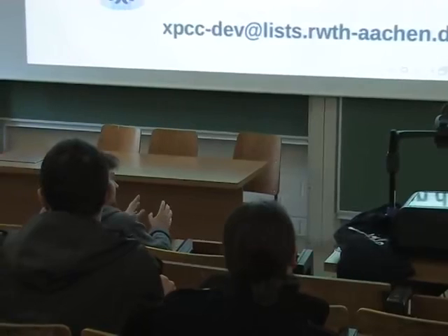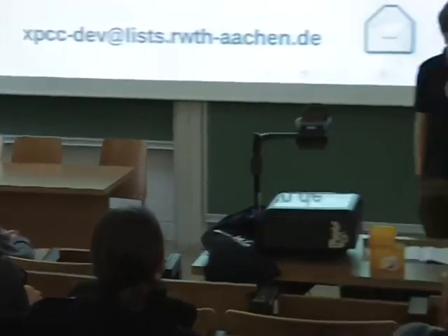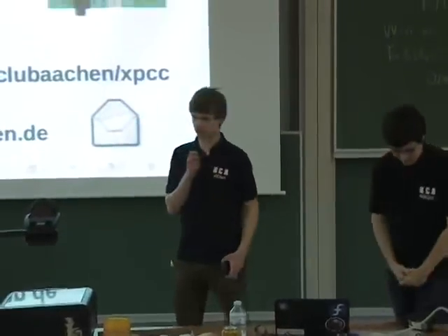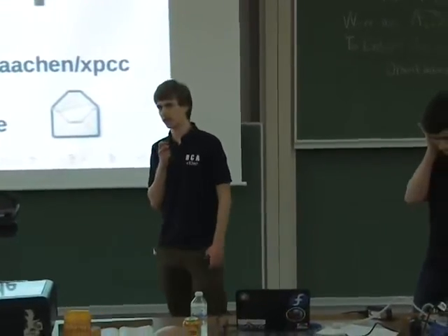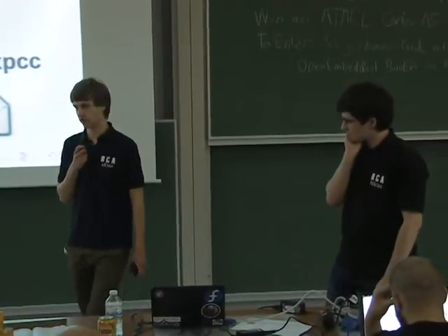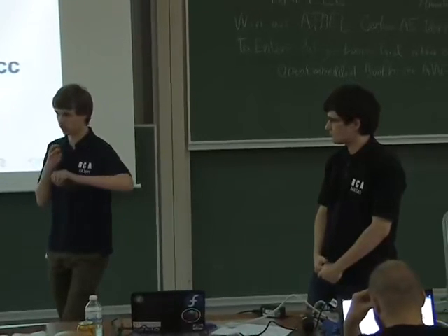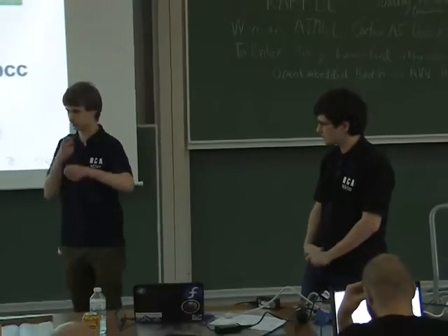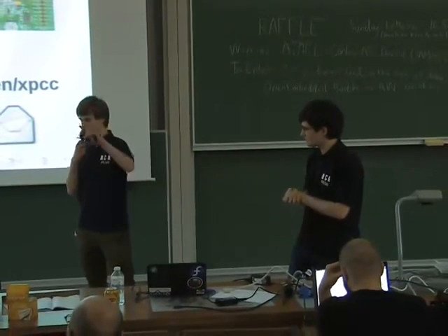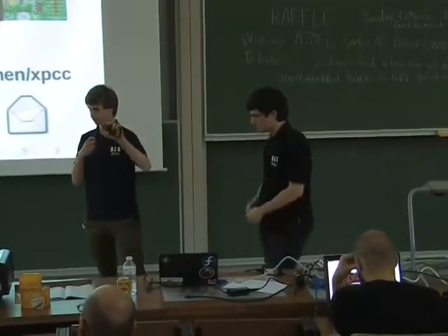Is there an overhead in terms of code size? Yes, I anticipated that question. You have to compare different ways of doing stuff. For example, when I got started with a new driver, I just added a DMA driver for the STM, and what I did first is I wrote everything to a register. That's the smallest you can get in code size, because it's all pre-calculated and just writes one value. And then I added like 3 methods to configure the DMA, because I thought it would be useful to have a general configure, then connect to a source, connect to a sink.